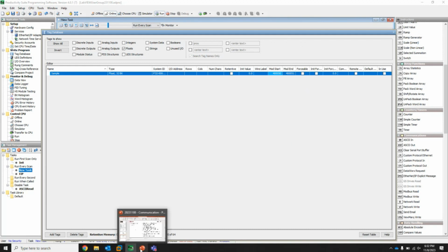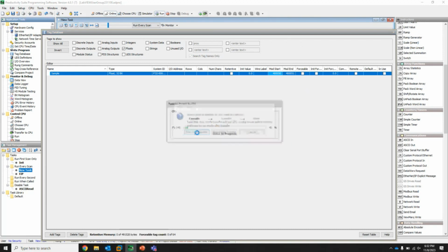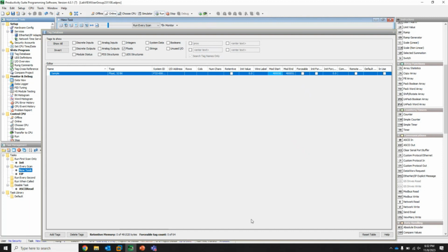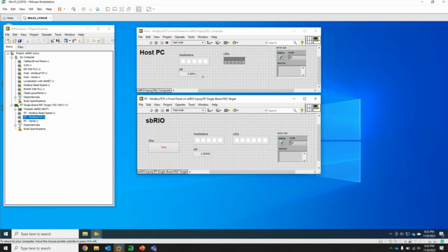One of the other catches here is this particular PLC starts its Modbus counting from 1. The LabVIEW library starts its counting from 0. So that can throw you off a time or two.